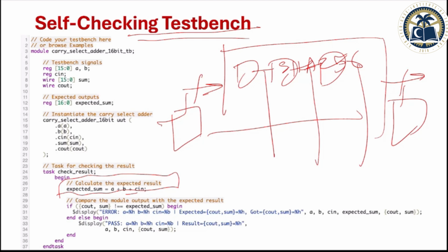But if you want to go inside the design, because you think that you don't want to do just black box testing, so I have tested all the pieces of the puzzle, all the pieces in the design, but I still want some intermediate values, okay? For example, you say, after the first iteration, what is the value of A in my SHA 256? So you also have to dump that into this file. If you're doing white box testing, find out everything you want to monitor inside your module, and all those variables are also there in your Python code. So once you're dumping your results into a file, whatever you think is important.